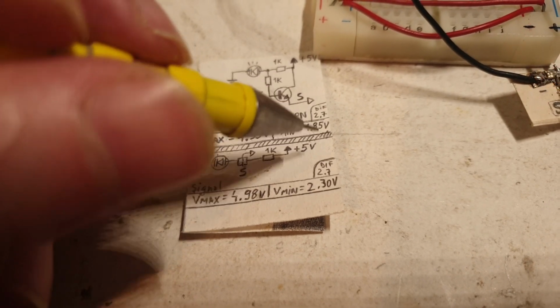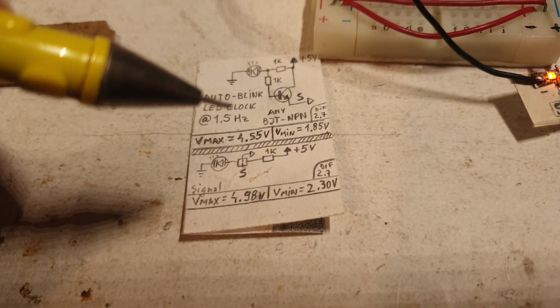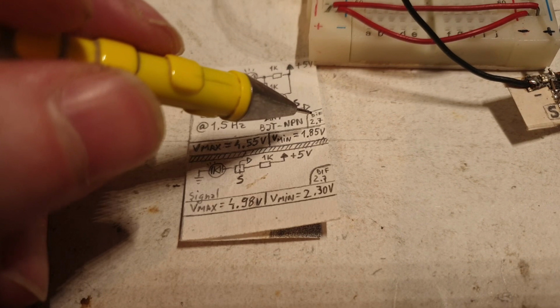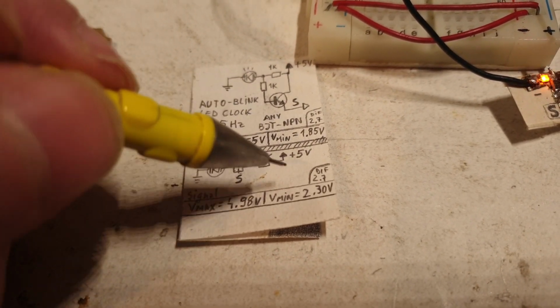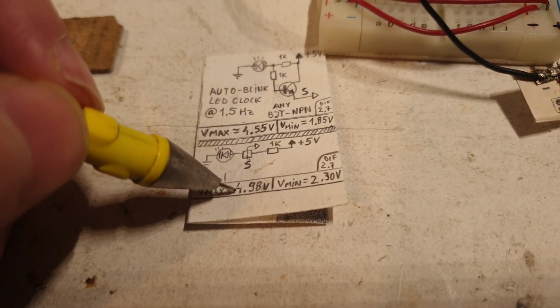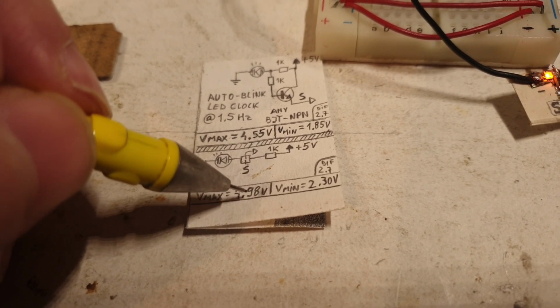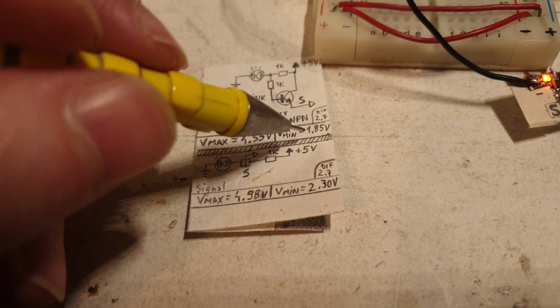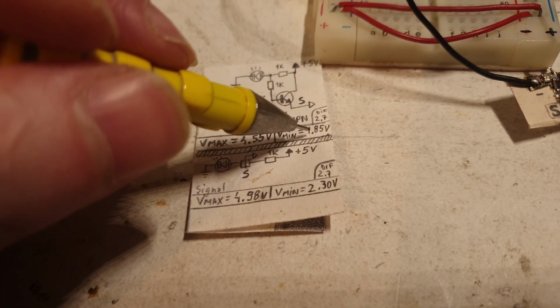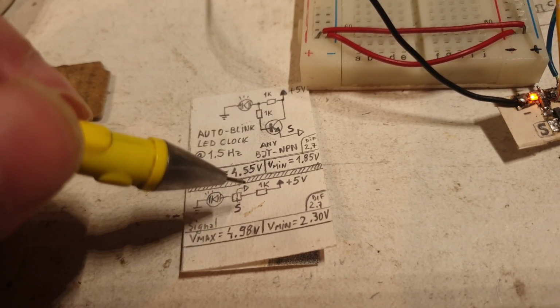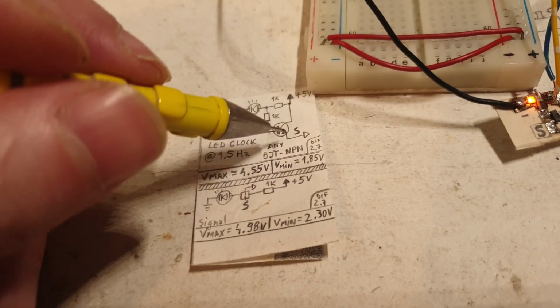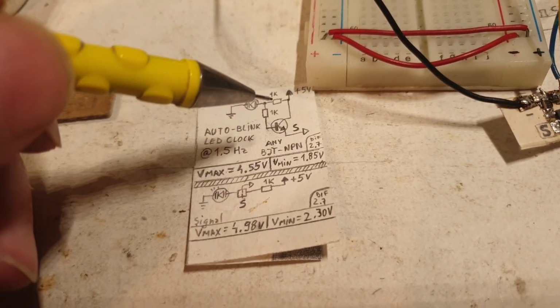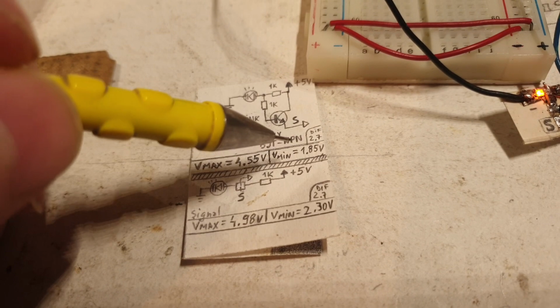This is a coincidence, most probably, but I was hoping for an increase in voltage difference. This here is too close to the voltage rail, almost 5 volts. But this minimum voltage is higher, while here it is lower, under 2 volts. Probably this minimum is lower because of the transistor, with the voltage drop over the base-emitter, or collector-emitter. I'm not completely sure, but it definitely got a lower voltage, this circuit.